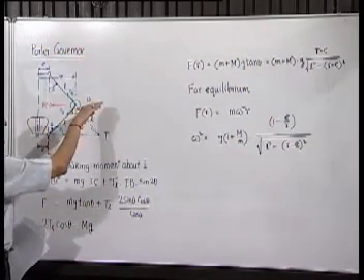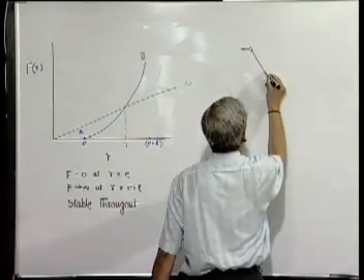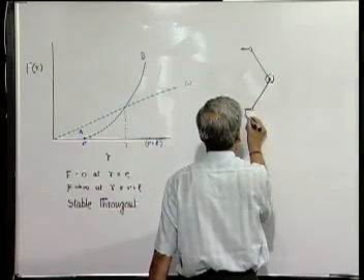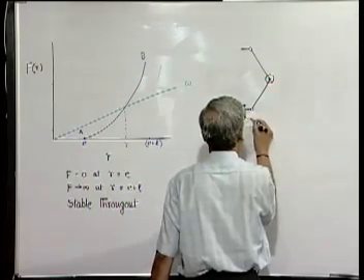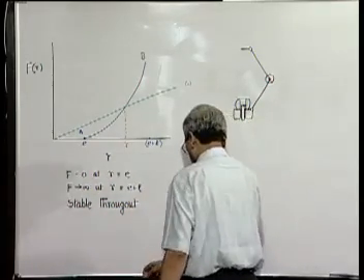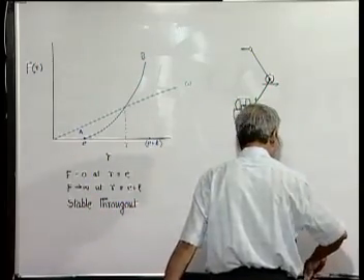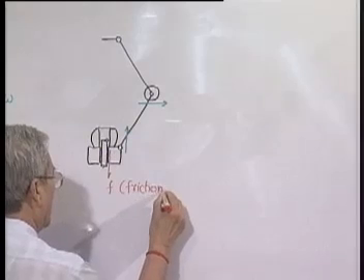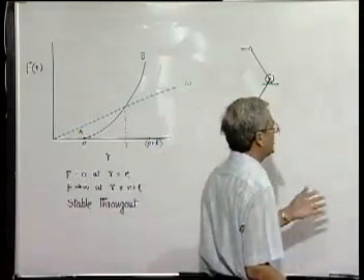So, when its speed is increasing, what will happen? It will try to move up, and so the friction, whatever friction there may be, so when it is speeding up, that means speed is increasing, then it has a tendency to move up, and so obviously sliding friction on the sleeve will be acting in this direction. This is the friction. So, what is the effect of friction on the whole thing? You will find the effect of friction is nothing but to add to the mass m here.